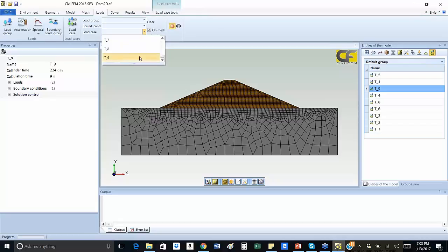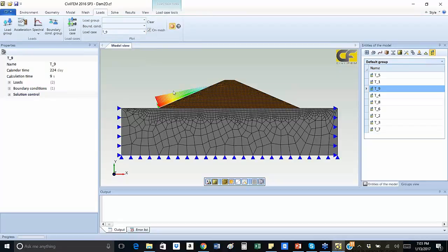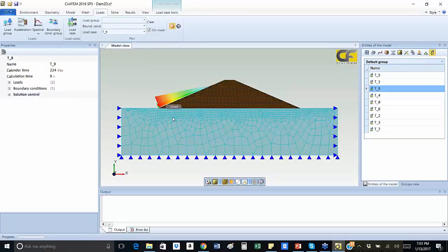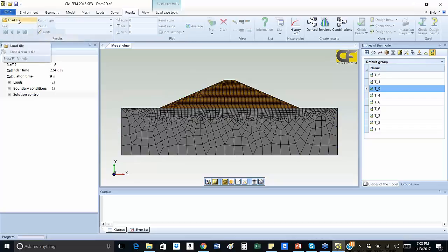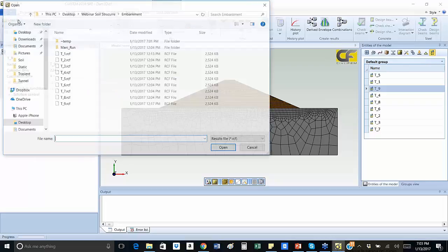Notice at the ninth stage, we see the hydrostatic load and its magnitude. Notice that the loads are perpendicular to the surface, as fluids have no shearing capacity or negligible capacity. Now we're ready to see the results for the first stage of construction.